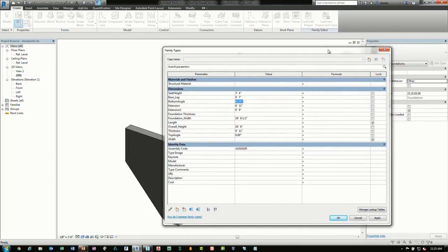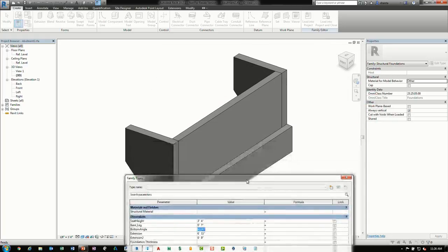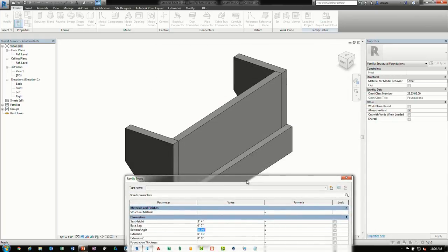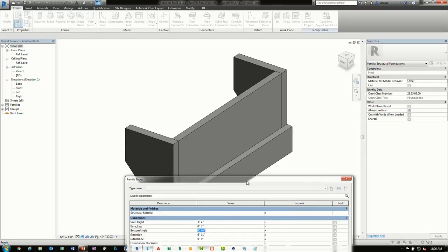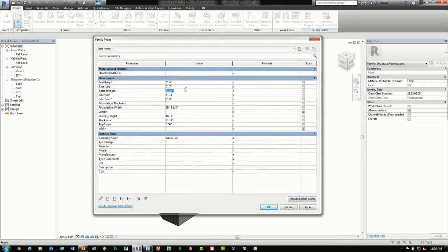that the naming convention of all of these families that get brought into Revit are very strange names. They're alphanumeric names, long sequences, 15, 20 character sequences. Very, very strange. I didn't particularly like the initial abutment 2 family that was brought over. It wasn't parametric in the sense of I can manipulate it and adjust the width, the length, the height, things like that. So I went and built it from scratch and still used the parametric information that came across.